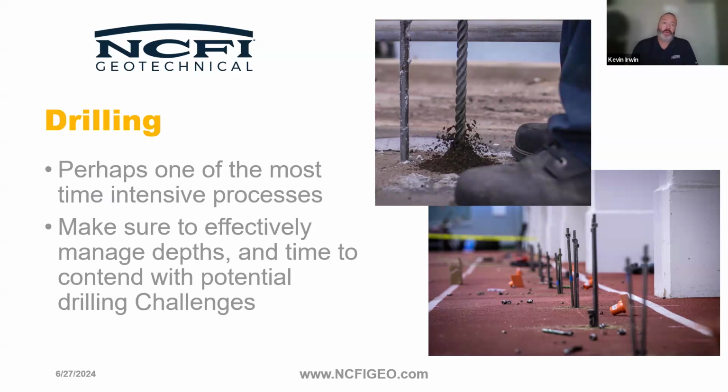We need to keep a seal around the outside of the tube as best we can to keep the injected chemical in the ground and not coming up around the annulus between the injection tube and the soil, where we just drop the injection tube through. So we want to make sure that we've got all those challenges worked out before we arrive on site.